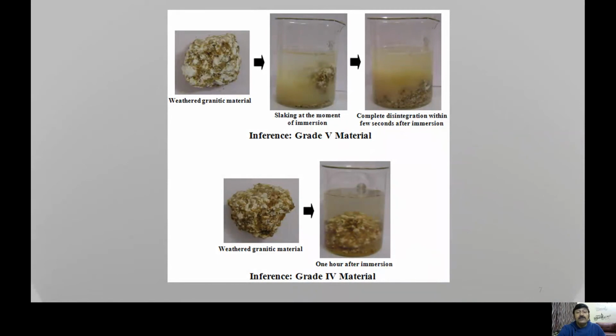However, we are not so lucky for other adjacent grades, and therefore we have to depend on some quantitative measurements. It cannot be solely based on the subjective criteria as given in the table of the six-fold classification. But we have to remember the first thing to categorize the weathering grades is to follow the six-fold classification scheme. And then we can refine that classification with the help of some quantification methods, like some index tests.